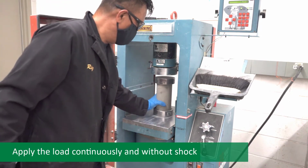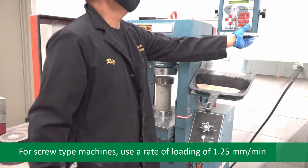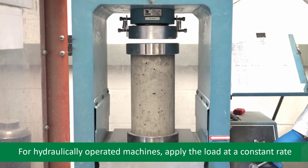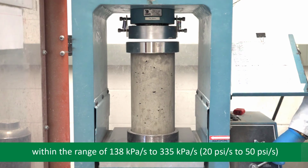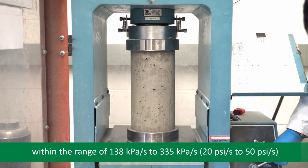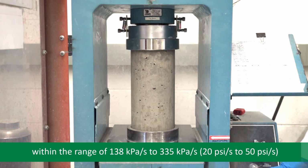Apply the load continuously and without shock. For screw-type machines, use a rate of loading of 1.25 millimeters per minute. For hydraulically operated machines, apply the load at a constant rate within the range of 138 kilopascals per second to 335 kilopascals per second, 20 psi per second to 50 psi per second, in other words.